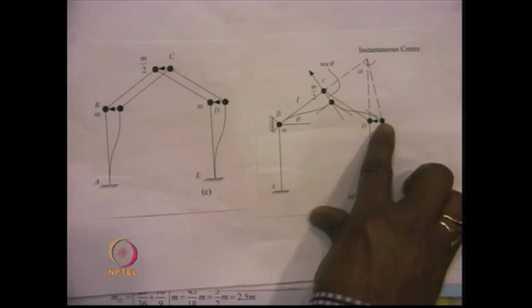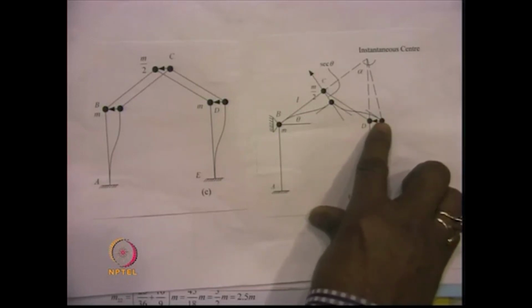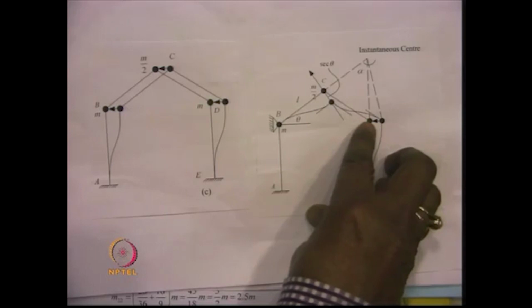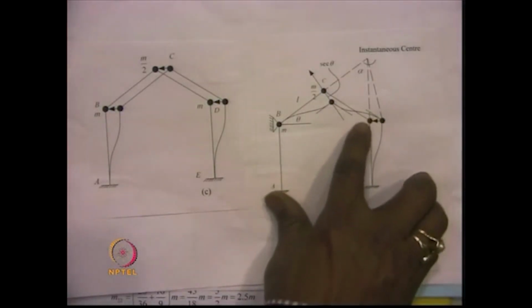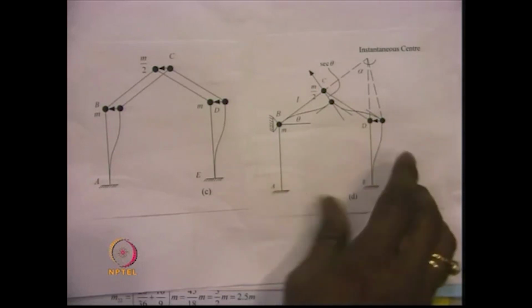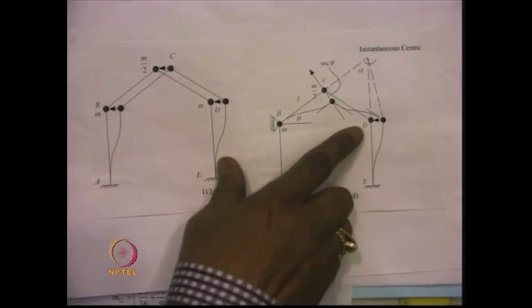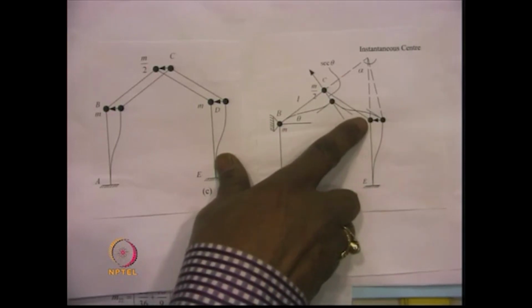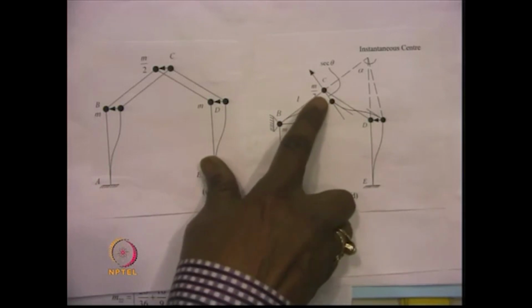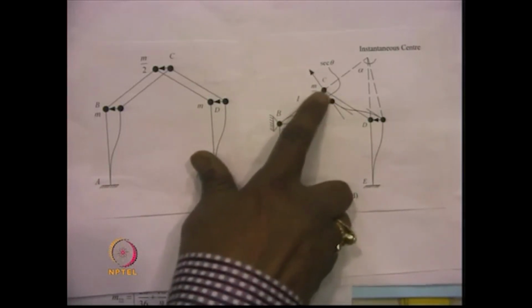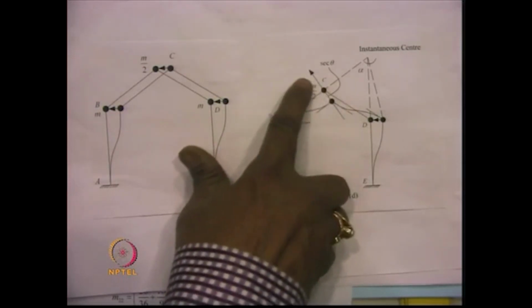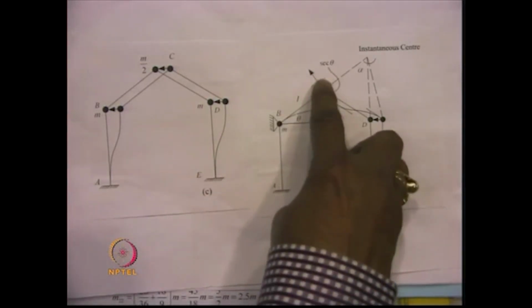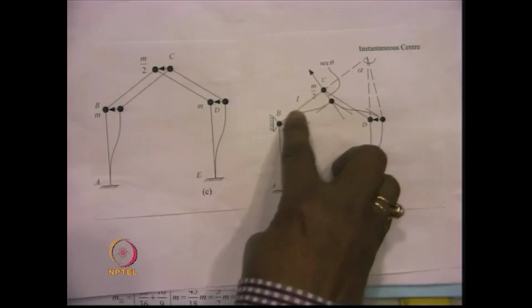Similarly, mass times the acceleration which will be produced over here because of the unit acceleration given over here will be the force which will be acting in the horizontal direction at this point. Since there is no degree of freedom which is defined at this point, this horizontal force will be decomposed, one into the vertical direction which will straight away go to the support. The other force will be resolved in this direction, this will be transferred to this particular point, and then this particular force which is acting along this member plus this force, these two forces will be resolved, one in the vertical direction, other along the direction of this member.